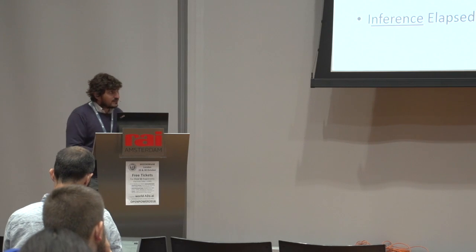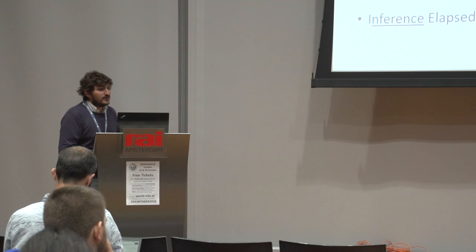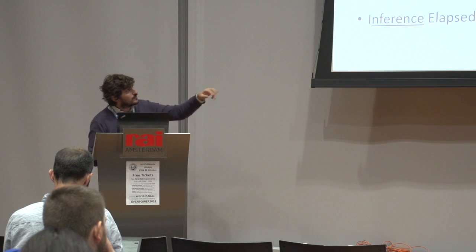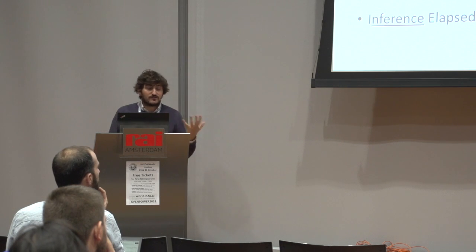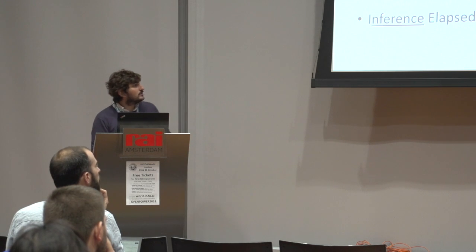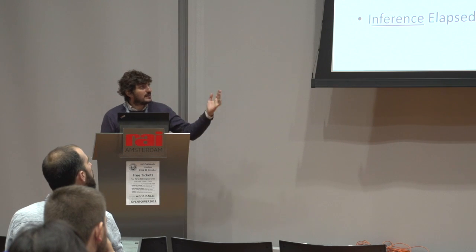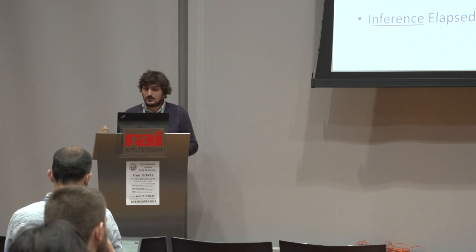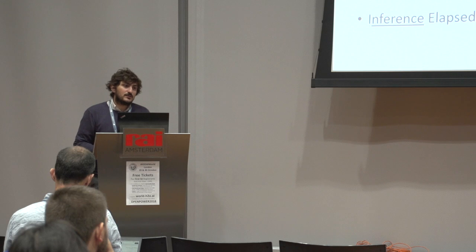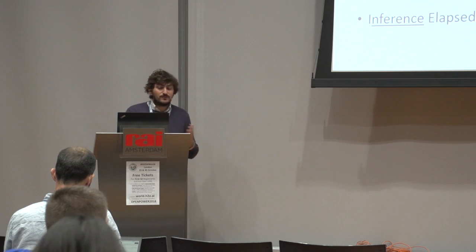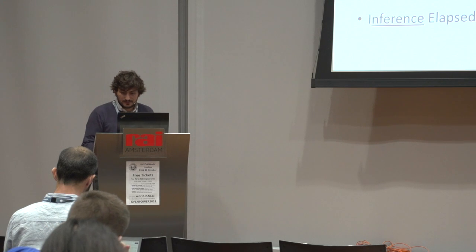So it's behaving well. We tested it on several nodes of Davide, and we have a good prediction of the normal and anomaly behaviors. We can also move this computation, the inference, within the embedded computers that we have on each of the nodes, so we can easily execute it with TensorFlow on the BeagleBone Black, with an inference time of 11 milliseconds, so we can actually do it live on the system. We can use MQTT to propagate whether the system is behaving normally or if it is misconfigured.